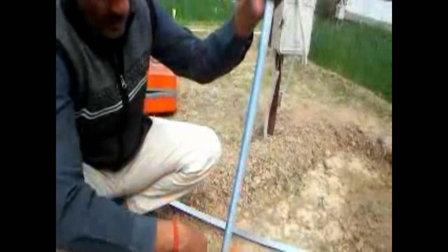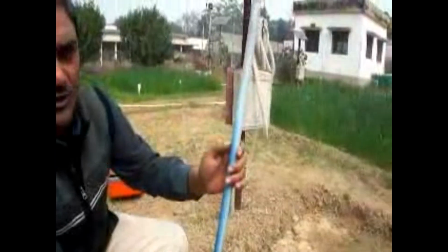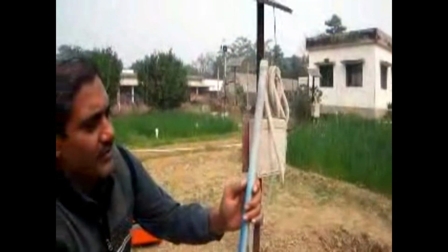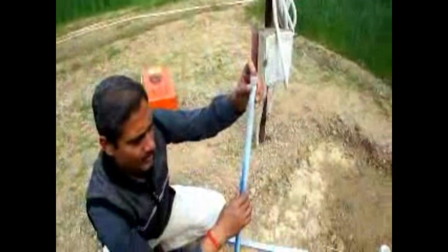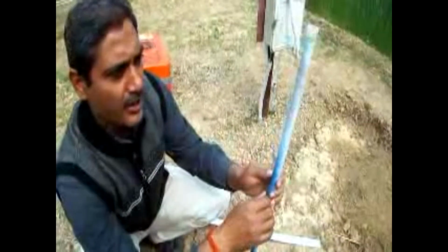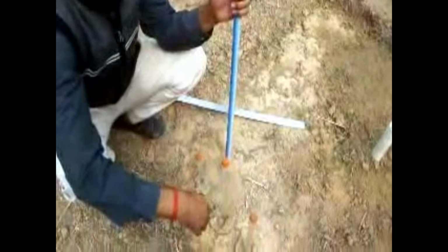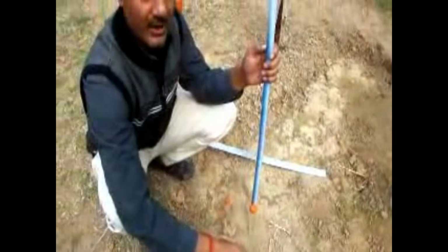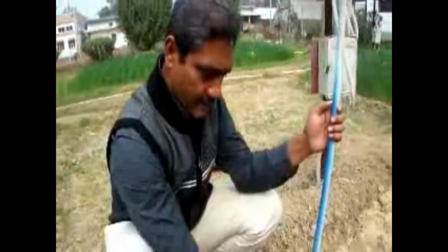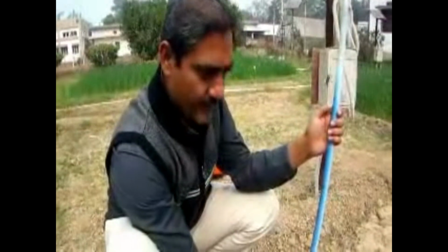Once water is getting out from the porous cup, it creates a suction in the tube. If we measure this suction in the tube by any approach, we can find out the suction condition, or hydraulic head, of the soil at the depth where we installed the porous cup.